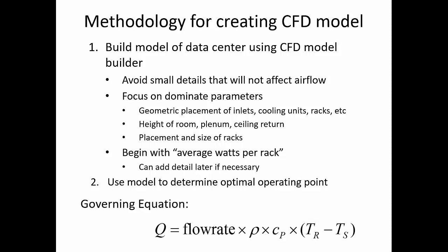Okay. The governing equation for all of this, by the way, is the convective heat transfer equation. Heat transfer is equal to mass flow rate times specific heat, in this case of air, or density times specific heat times delta T. This delta T is the return-supply delta.